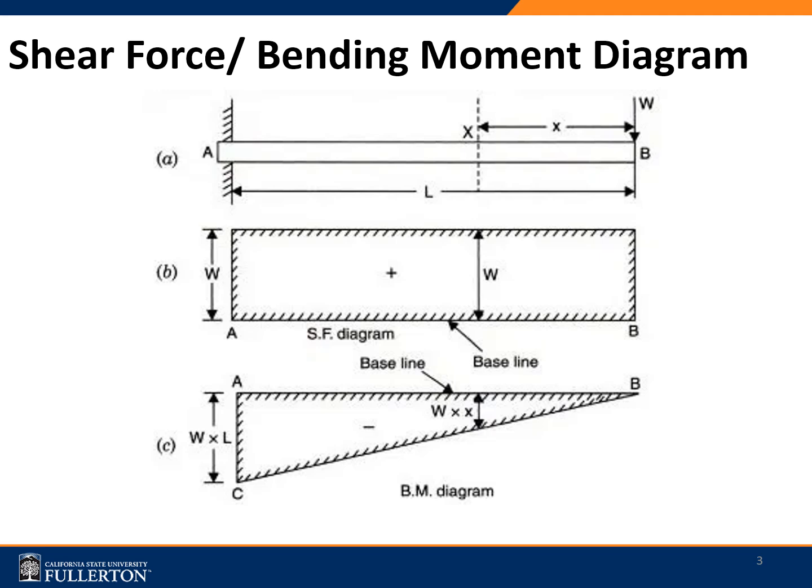Now the bending moment of a cantilever beam is maximum at the fixed end, and it decreases to 0 at the free end. The bending moment as well as the shear force diagrams are determined for all possible combinations of loads, and that would help to design the cantilever beam for a specific structure. The load applied on the beam is a combination of the dead load as well as the live load, as per the design standards when we perform the design process.